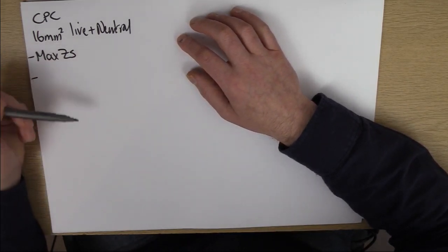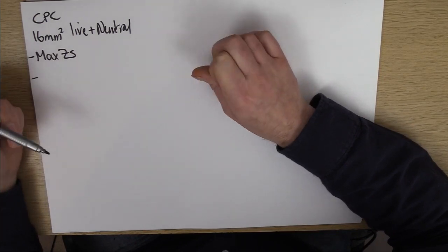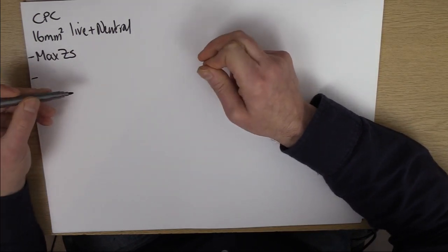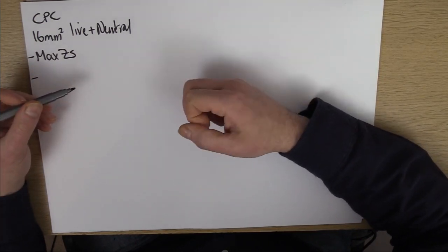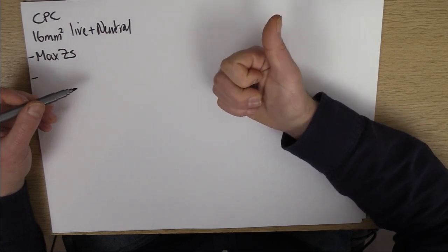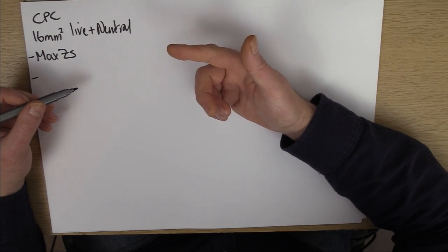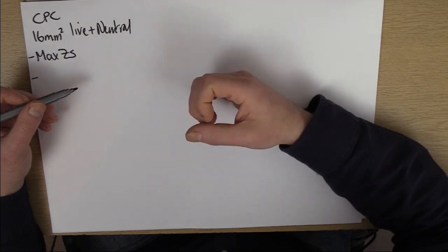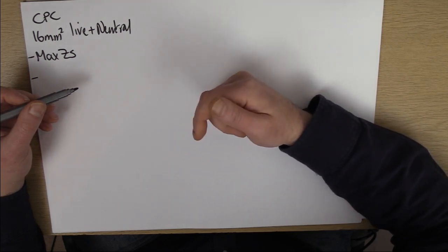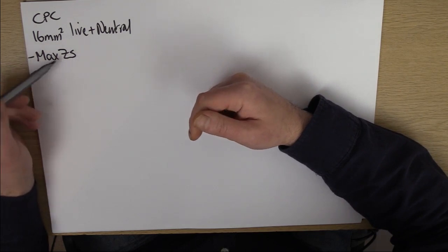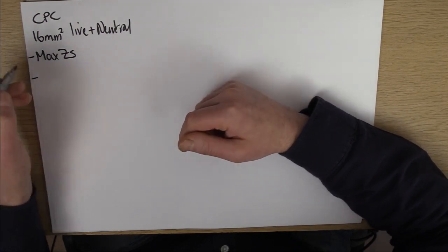So again, there's two methods. We can either just take a stab in the dark and check it for compliance, or we can rearrange and find out our maximum R1 plus R2, which in turn tells us our maximum milliohm per meter value, and then we can choose a cable fairly quickly that way. So first step then, we need our maximum ZS.